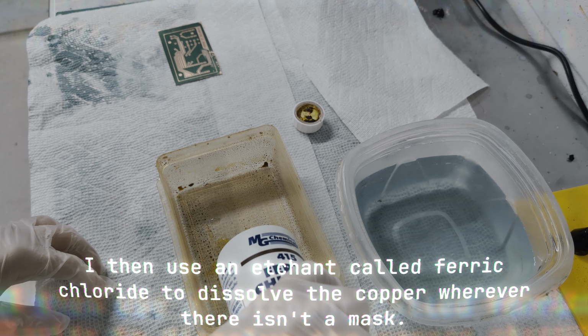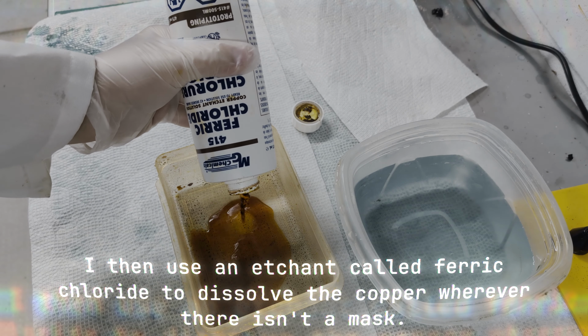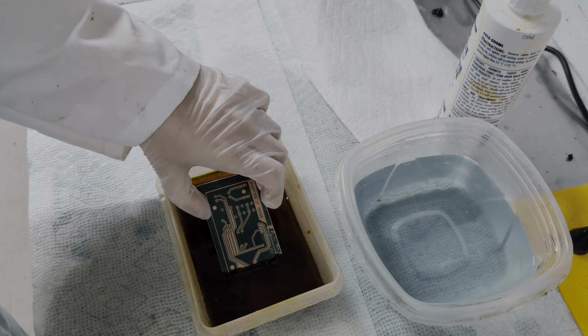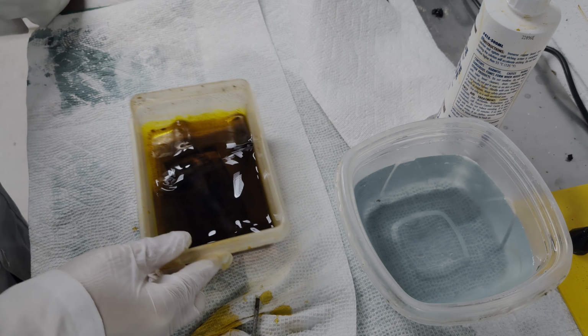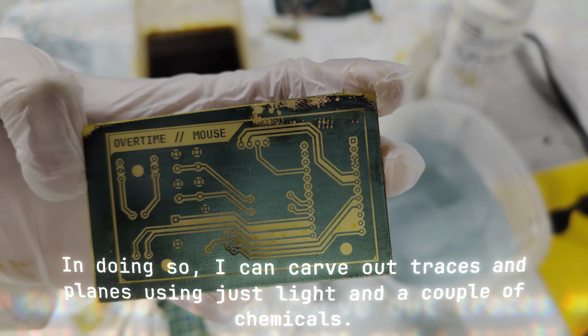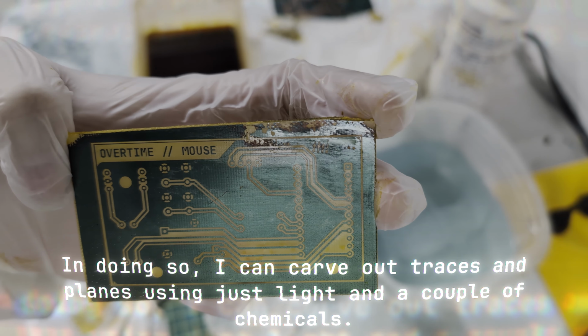I then use an etchant called ferric chloride to dissolve the copper wherever there isn't a mask. In doing so, I can carve out traces and planes using just light and a couple of chemicals.